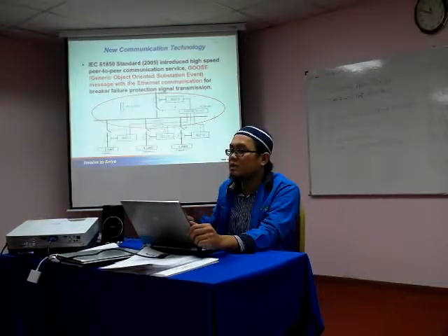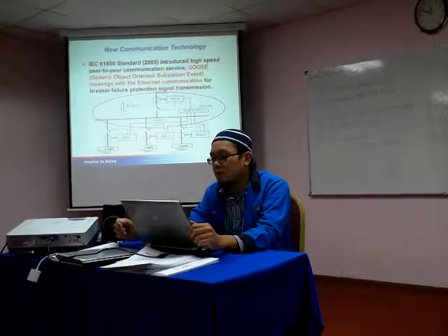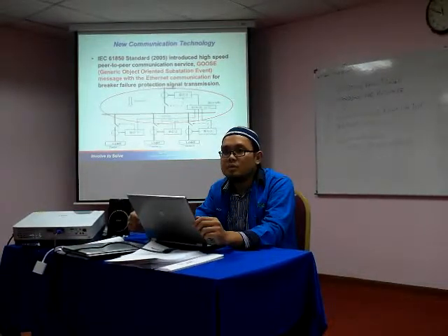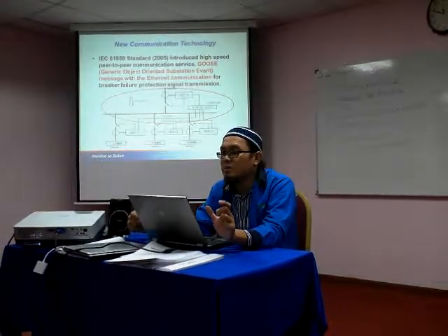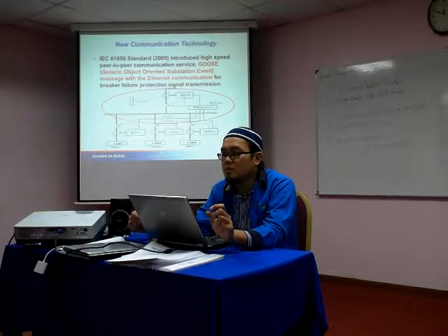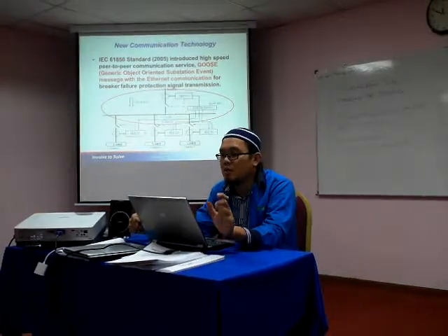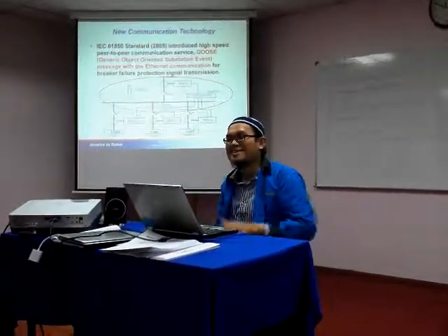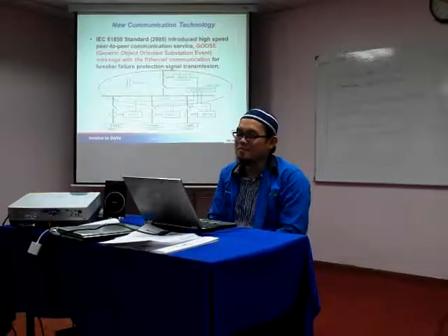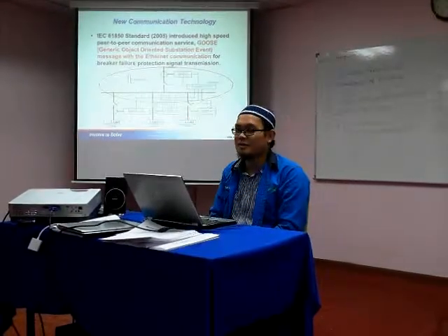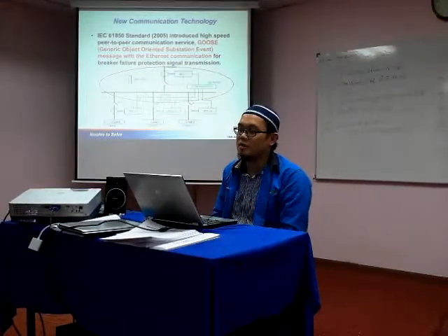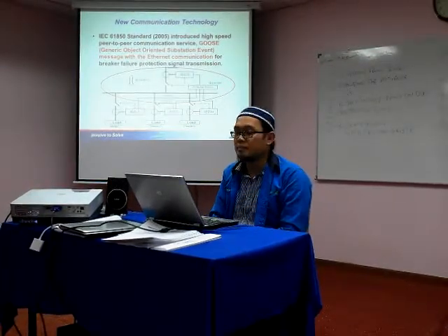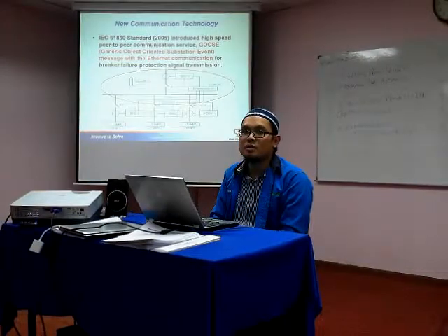The standard is based on the IEC 61850 standard introduced in 2005. This standard introduced a new communication service named GOOSE, not the animal, but generic. GOOSE stands for Generic Object Oriented Substation Event. This is one of the communication profiles introduced by the standard.